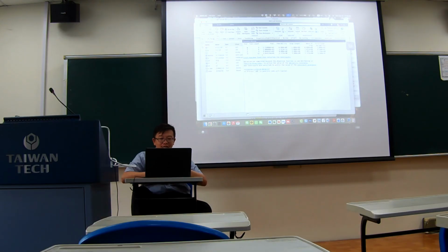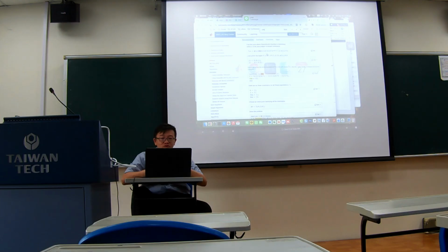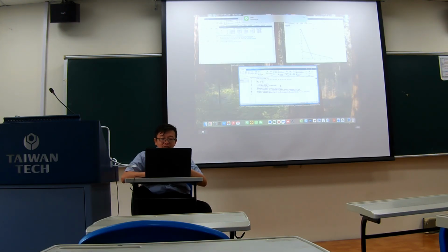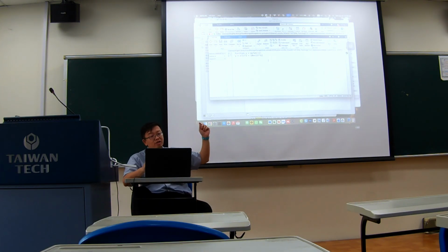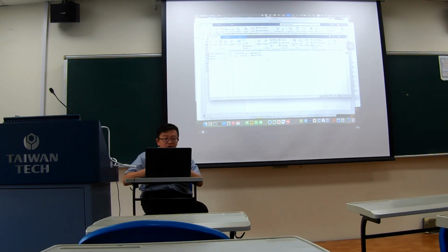So that's the optimization process, but you cannot see it, right? So what can you do to see it? Every time you go into this fmincon, it will call the function values. We call this file. Every time you come here, you plot out the position. So you can say plot x1 and x2 with a small red circle.